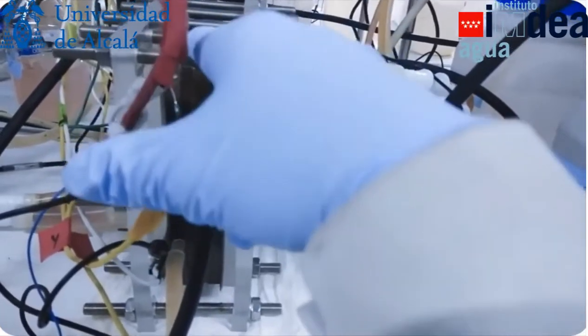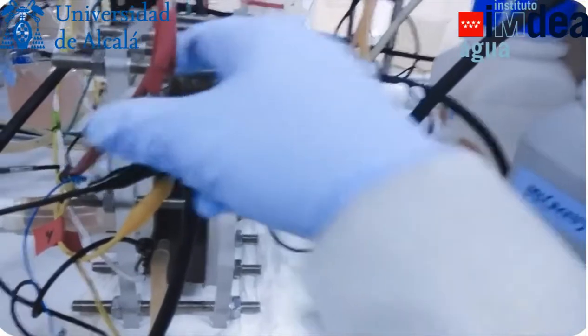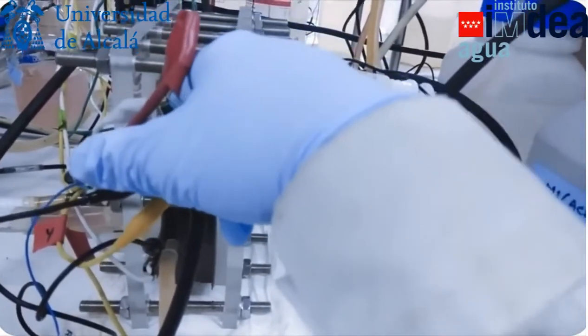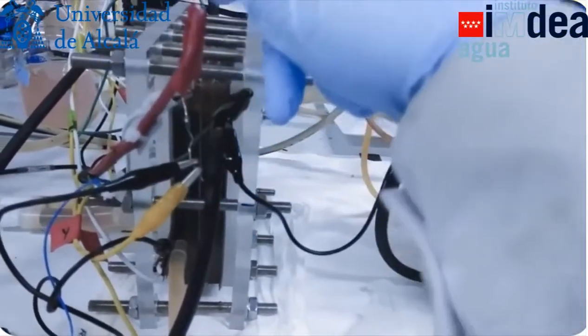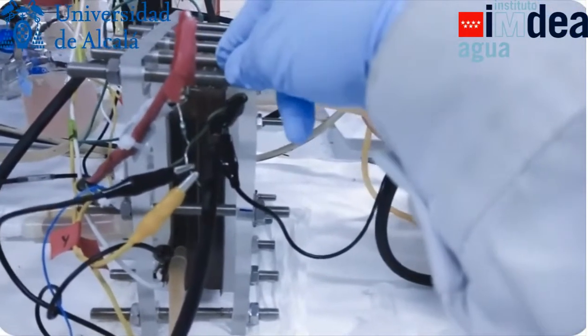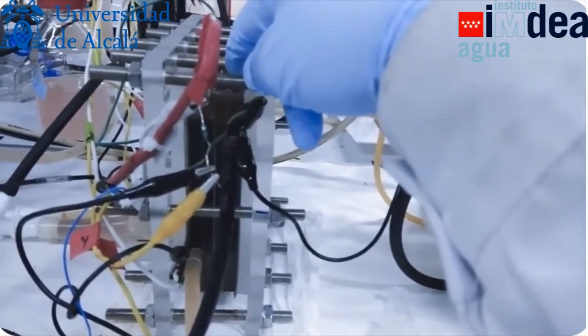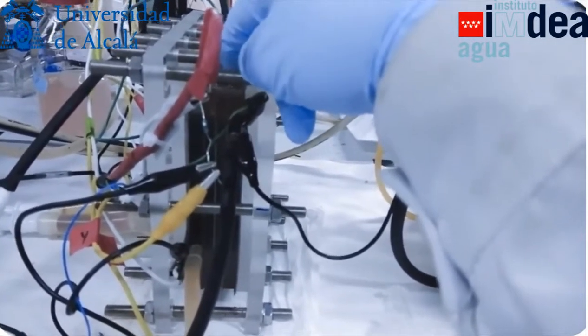Hence, H+ ions cannot cross over this anion exchange membrane to the cathode. Thus, they will be trapped in chamber A itself. Similarly, OH- ions also cannot migrate toward the anode chamber, since chamber B and the anode chamber are separated through a cation exchange membrane. Thus, they will be trapped in chamber B.